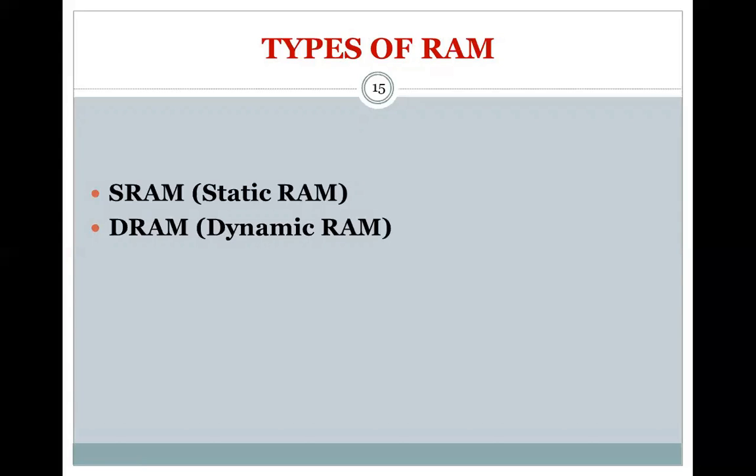If the power is turned off, the contents will be lost in both SRAM and DRAM, because both SRAM and DRAM are volatile. Only static RAM, because of the data reinforcement, gives exact data when read out. Then dynamic RAM has a short data lifetime because it uses a capacitor and one transistor.